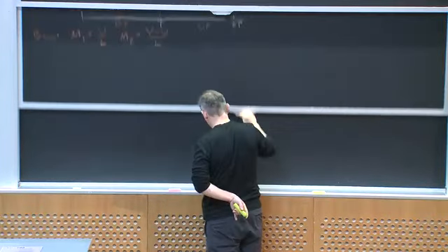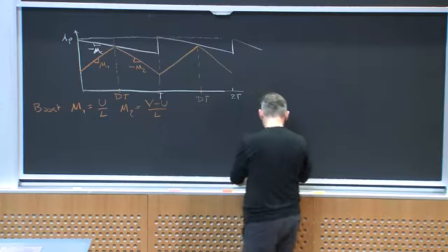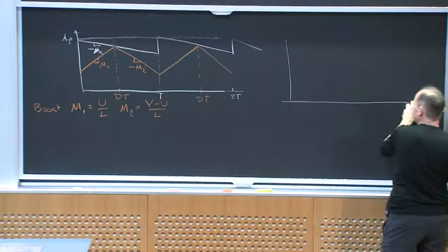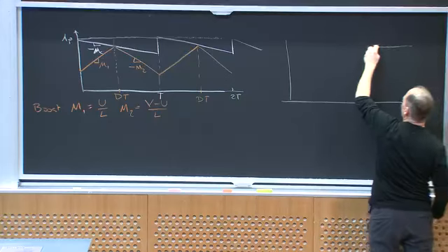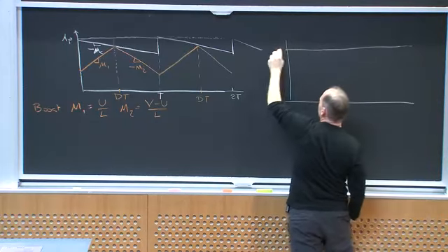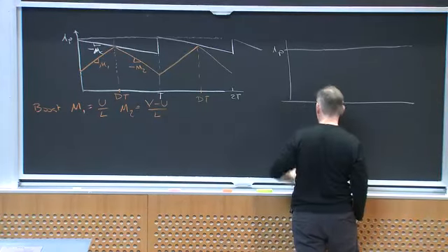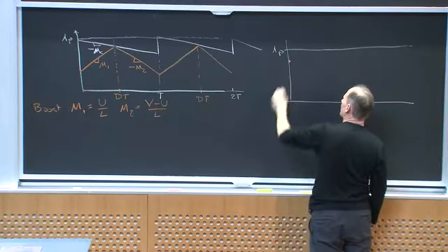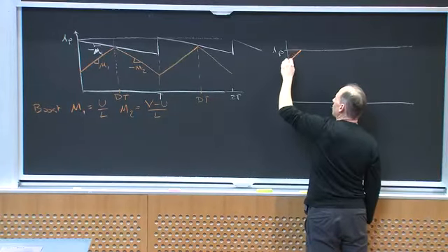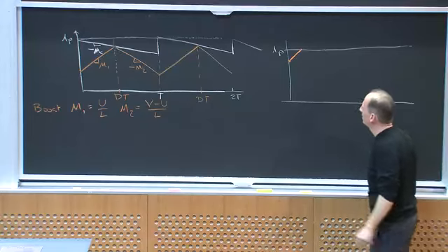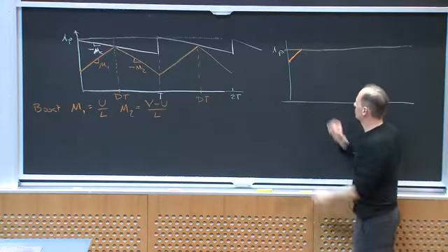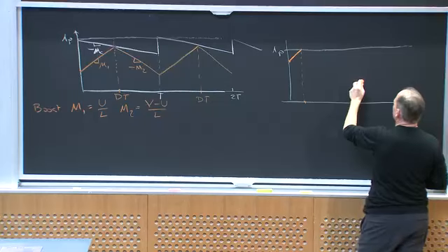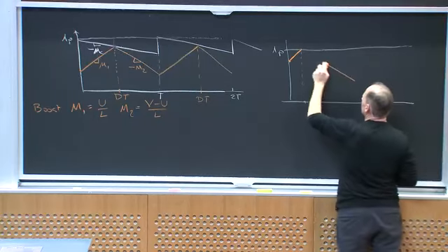In some cases, if I do that, this is the situation I can find myself in. I'm going along, and suppose I just have I_peak and I get rid of the compensating ramp. So I'm at the beginning of my cycle, and here's my inductor current. I turn on my switch, I go up and I hit the top, and I trip. So this is my duty ratio in this cycle, and I turn off till the end of the cycle.